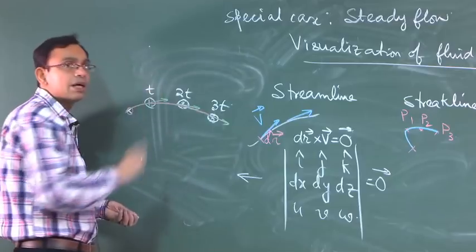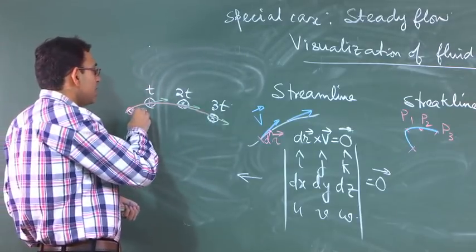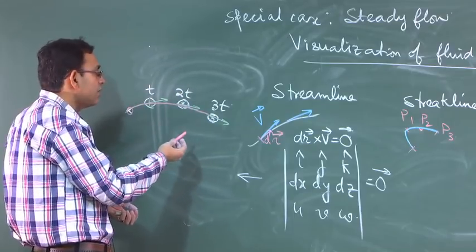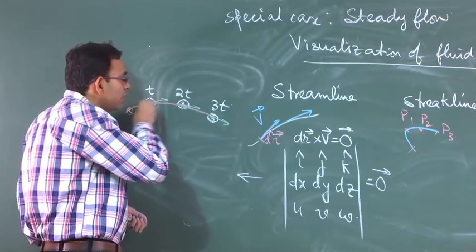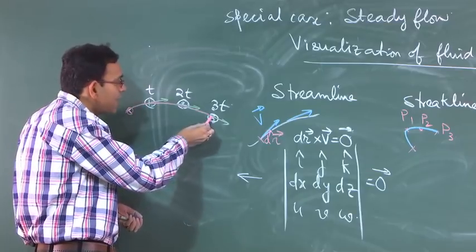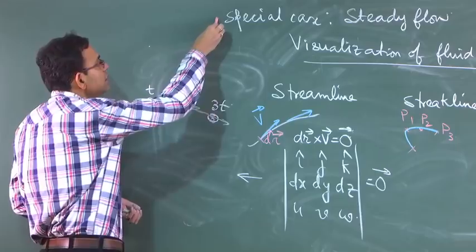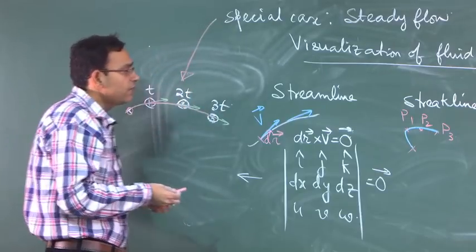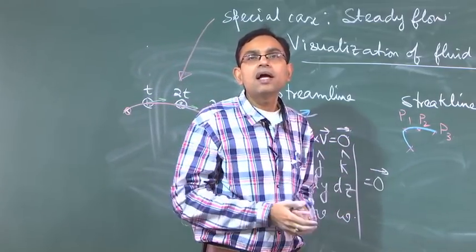So, this will also become the streamline, and because the particle trajectories will not change with time in a steady flow, whatever particles have passed through this point will be constrained to move along this only. Therefore, the same line may be represented as streamline, streak line or path line. Therefore, for steady flow, streamline, streak line and path line are all identical.